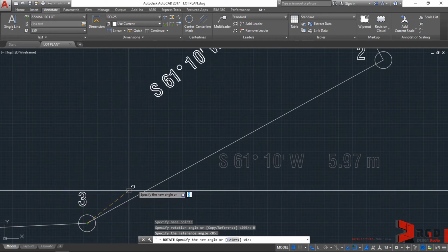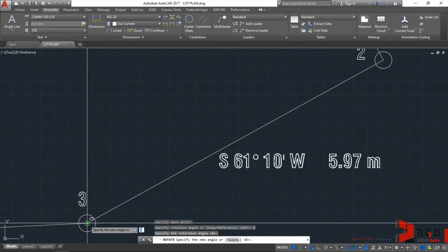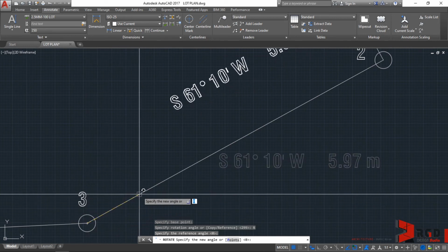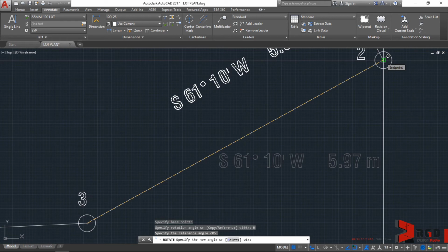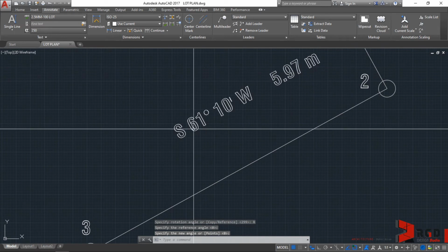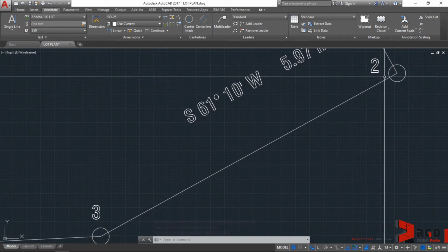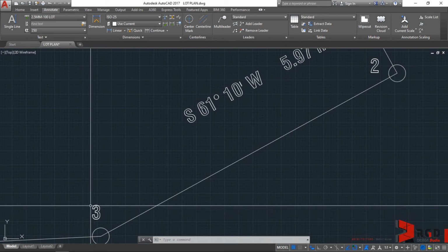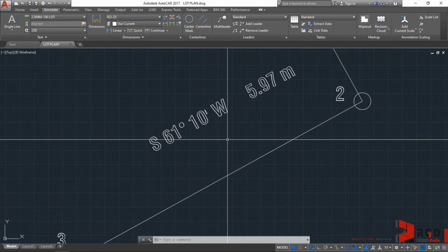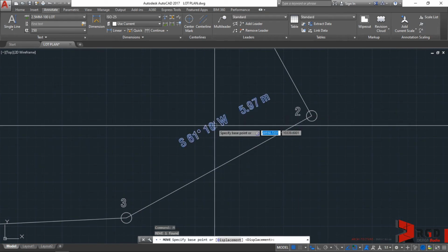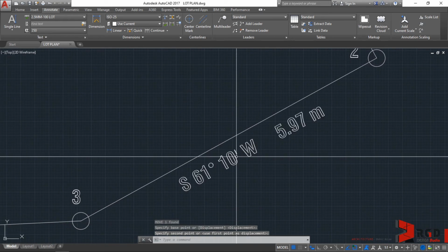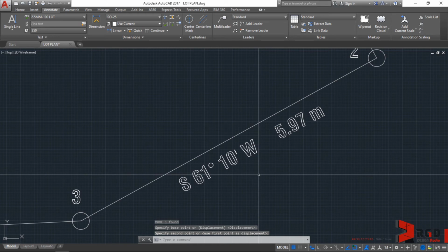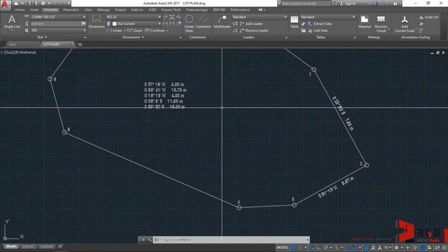You just drag, from the initial base point that we have selected, we drag our cursor towards point 2. So until endpoint appears, snap to that endpoint. So click. So we are assured that this line is perfectly aligned to line 2-3. Albeit it has a far distance from the line, we just move it. So M, enter, then just move it just so. And then for the rest, let's move and then rotate them also.